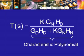There is a numerator of this T(s), Gn into Hd, which is a mixture which has the numerator part of G, but it has the denominator part of H. Now, this numerator also can have influence on the response, but I am not going to look at it, it is more involved, and these contribute the zeros of T(s).